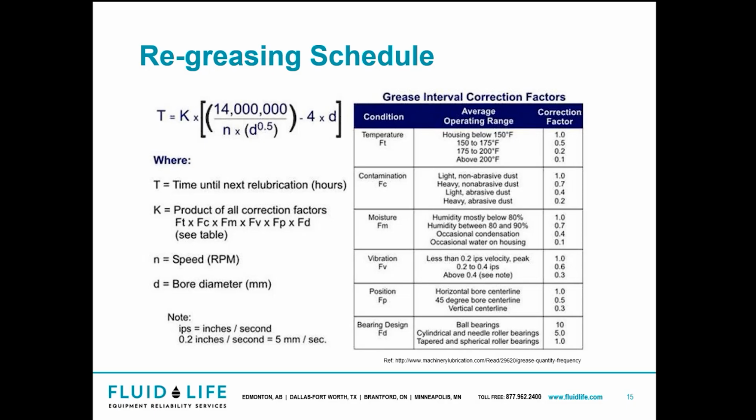And when I say greasing schedule, you take all these constant factors and you plug them into this calculation. It seems like a daunting calculation, but it's really not that difficult. You can make this in Excel pretty easily. In fact, we have greasing calculators with Fluid Life built to help with the volume and the quantity. And this also tells you how often you should be greasing it.